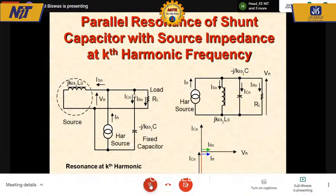If I connect a filter here tuned at the 7th harmonic, there is a chance that at the 5th harmonic this might resonate, because the 7th harmonic filter will behave as a capacitor at the 5th harmonic, and it can resonate with the source. So this is a risk that we always run with the system because of the presence of harmonics, and the harmonics are created by us only because of the use of power converters.